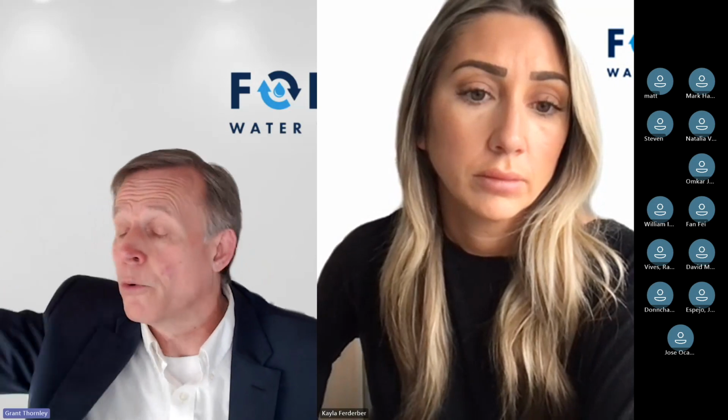If it's low lithium, I'm going to go with titanium. I'm not saying that's the only reason you could use titanium, from 50 all the way up to 1,000 ppm, but for lithium aluminate double hydroxide, I would start around 100, 130, 150. That's where I see the economics.